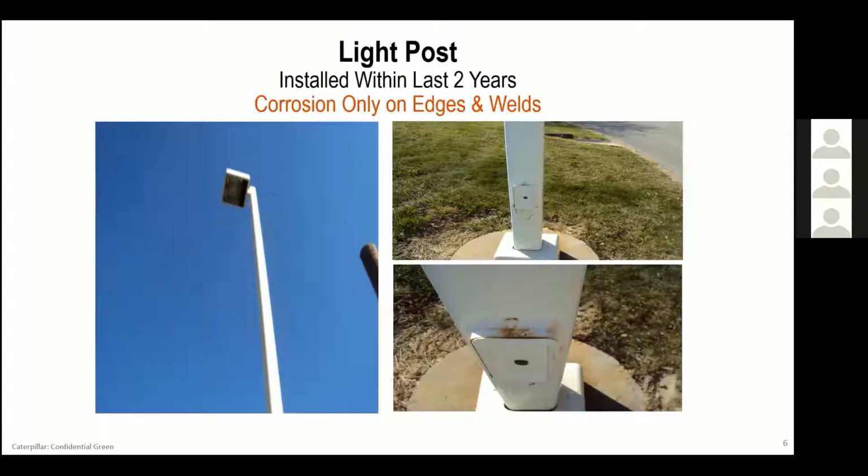The same held true as I went to one of the hospitals. I knew that in the last couple of years prior to taking these pictures, they'd put these new light posts in, and from afar it looks great. And sure enough, when I go down to the area where maybe there's an access panel, or with edges and welds, you see where obviously there's some corrosion.